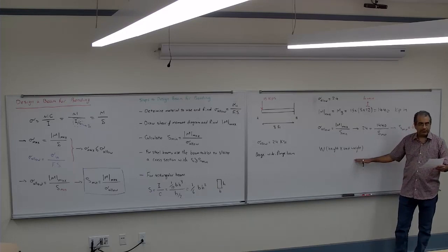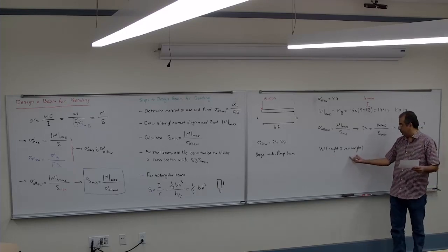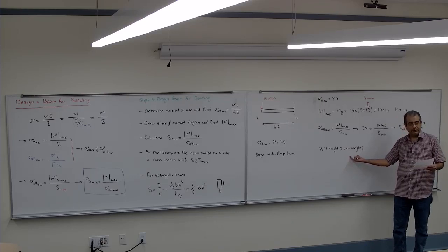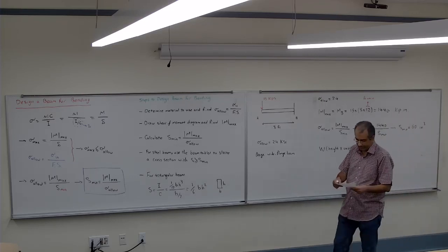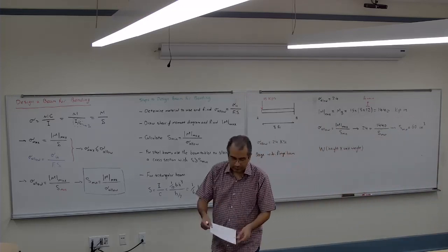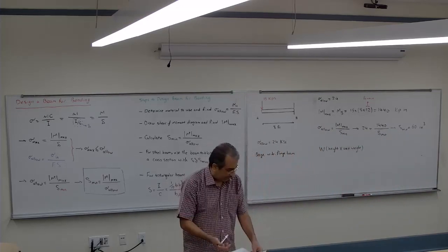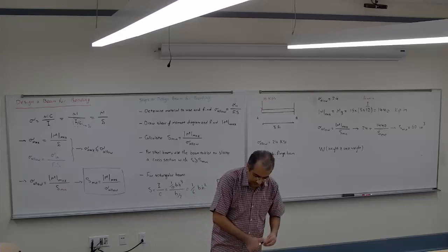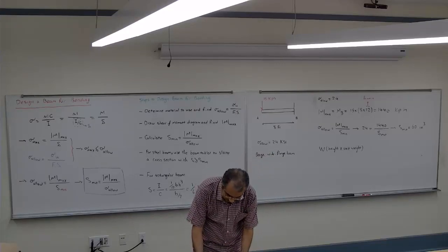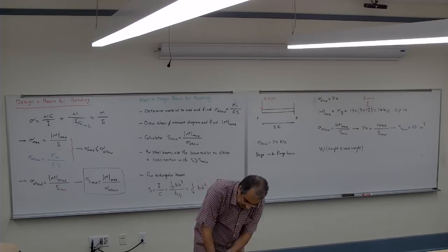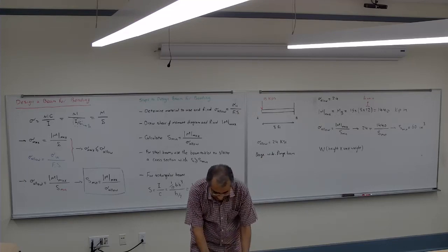So usually you will go after the one that has the smallest unit weight, because you want to make it as light as possible. So there are many possibilities there where the S is 60 or more, but if you look at the table, the one that you probably have to go after is W 16 by 40.